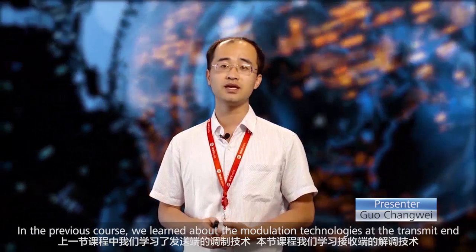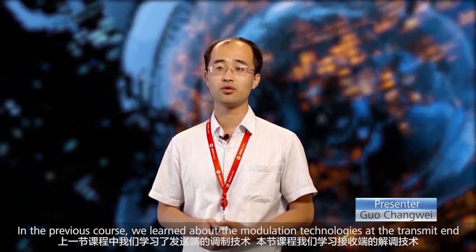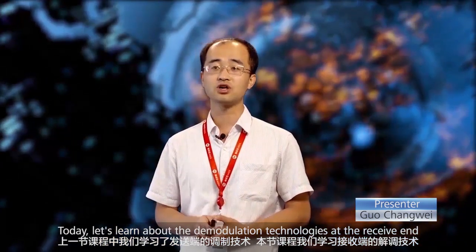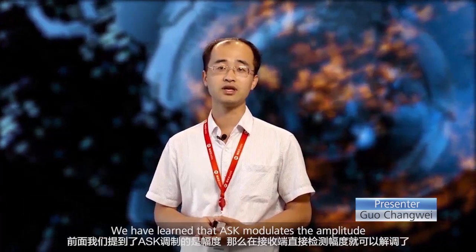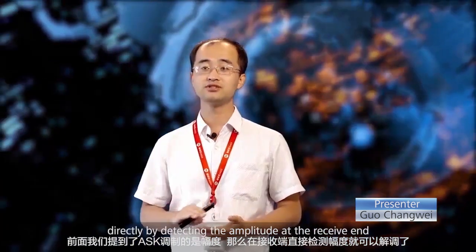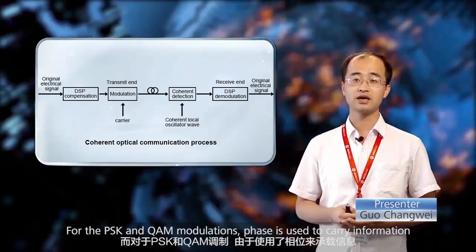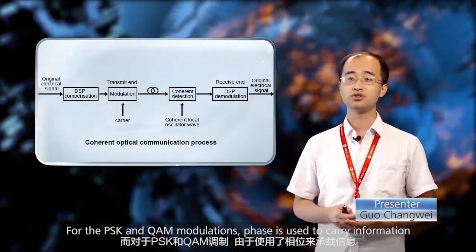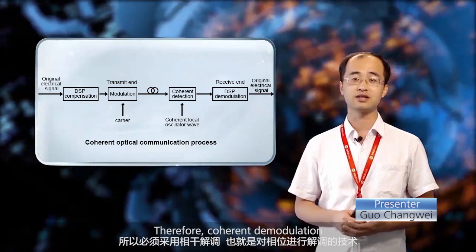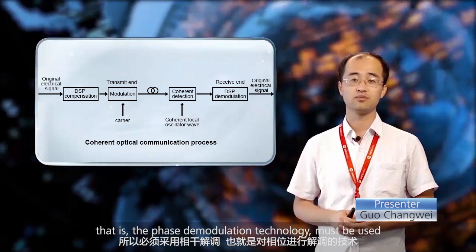In the previous course, we learned about the modulation technologies at the transmit end. Today, let's learn about the demodulation technologies at the receive end. We have learned the ASK modulates the amplitude. Demodulation can be implemented directly by detecting the amplitude at the receive end. For the PSK and QAM modulations, phase is used to carry information. Therefore, coherent demodulation, the phase demodulation technology, must be used.